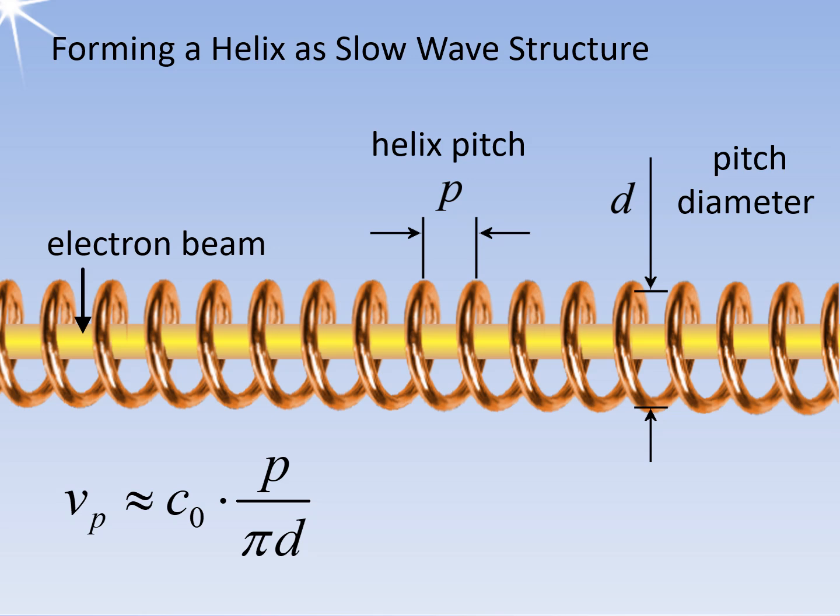The electron beam is focused by the strong permanent magnetic field. The magnetic field prevents the electrons in the beam from repelling each other. Without any high-frequency input signal, the electron beam maintains a uniform density and speed of electrons. The speed of an electron in the beam is the square root of the electron charge 2e, where e is 1.602 times 10 to the power of minus 19 coulomb, divided by the mass of an electron, m, which is 9.109 times 10 to the power of minus 31 kilogram, multiplied with the anode voltage Va.